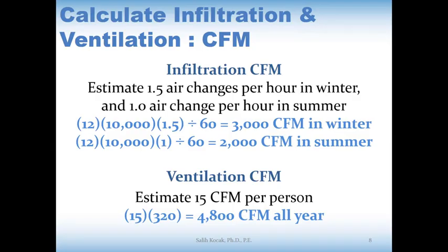There are a few things actually. Most of the time this is a very basic calculation that we are doing, but you have to be careful about the ventilation fans. They pressurize the building, and finally they overcome the anticipated infiltration. Since they are pressurizing it, they really overcome whatever infiltration we are anticipating. But still, this type of calculation should be fine.